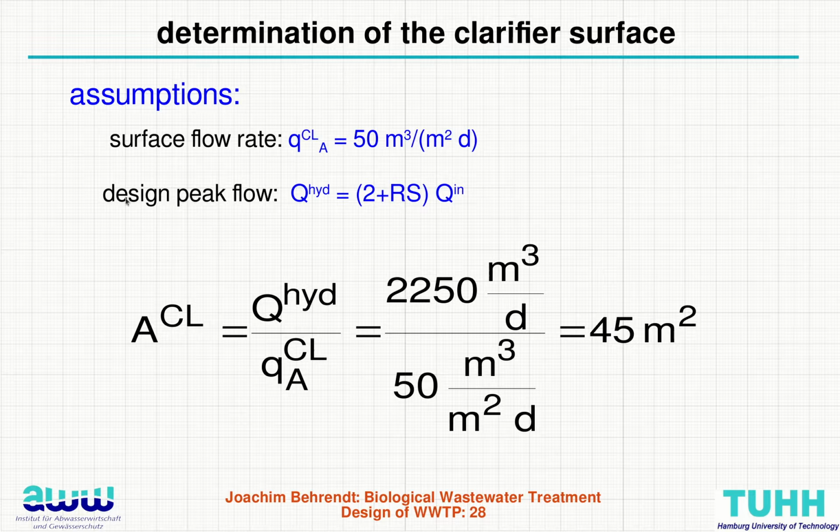And we also have to calculate the hydraulic flow, the peak flows, to the clarifier. There we are calculating with the hydraulic inflow of 2 times Q in, and the return sludge flow is also clarified. Also this 3 times Q in is used in the clarifier.